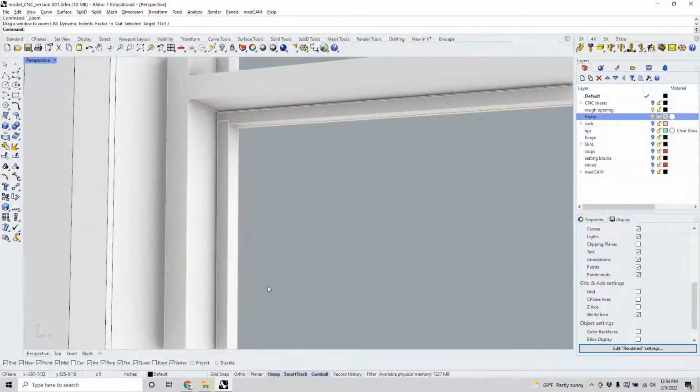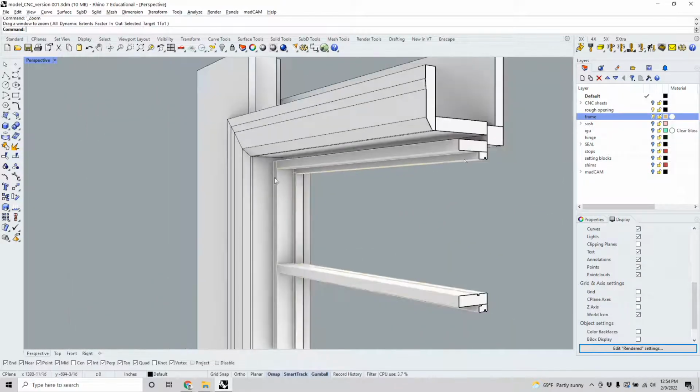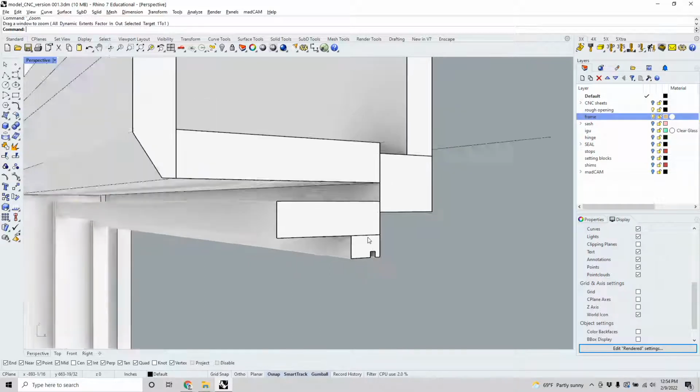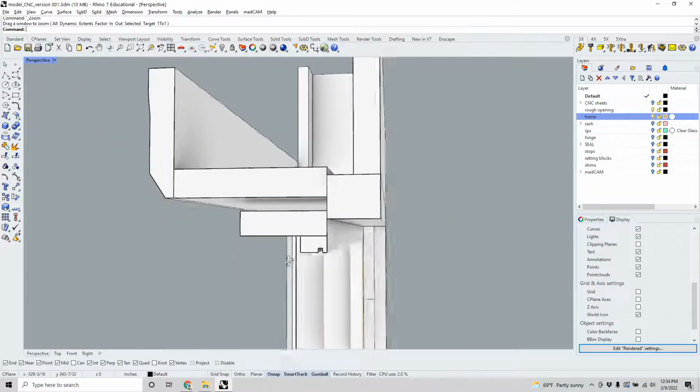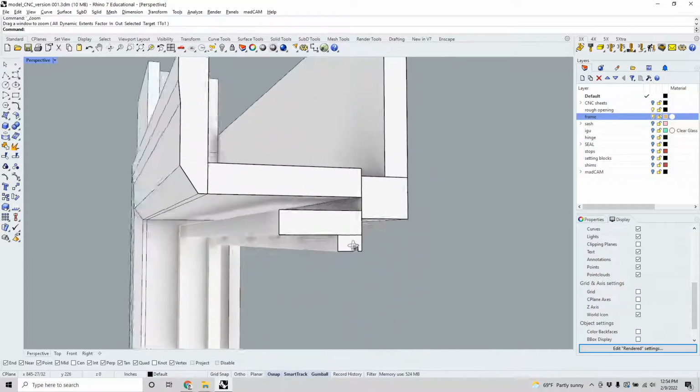Okay, going back to the head, and taking a look at the section here. This is that main 3/4 piece at the head, and this is that half-inch thickness. And what you'll see is that I've cut a curve into this so that this becomes a drip edge, such that if any water flows down and over, there's a lip for it to drip off of.